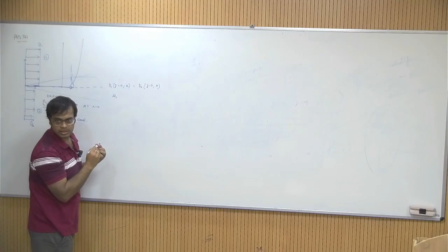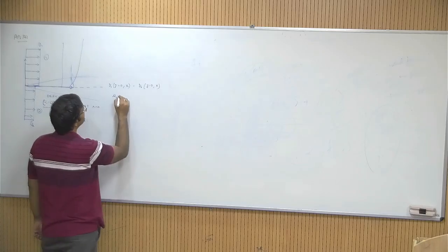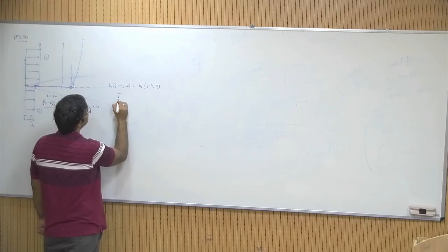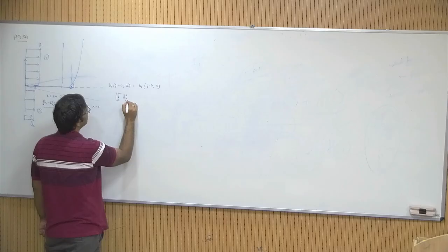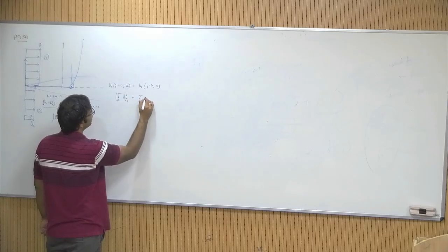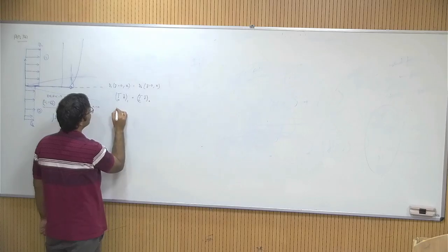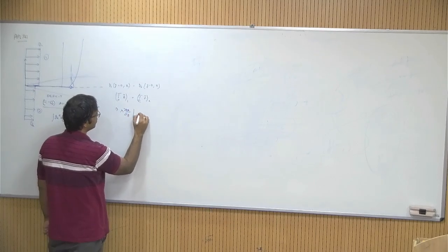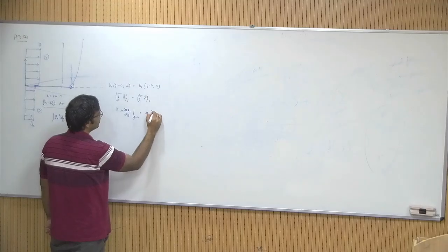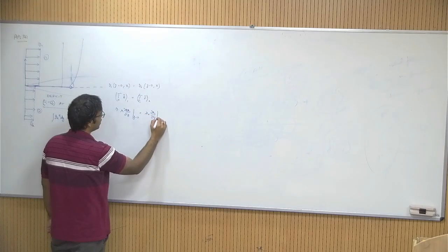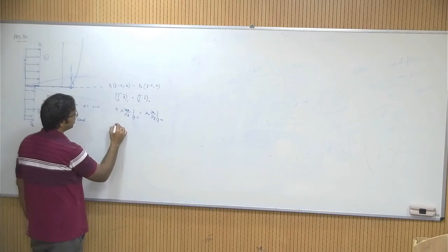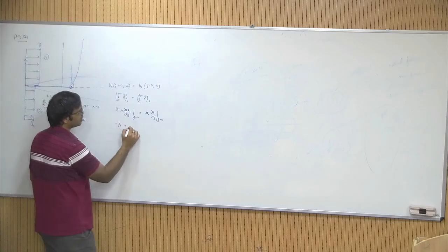and then there is another boundary condition for an interface, which is from the stress equality. So you have basically T dot n at 1 is T dot n at 2, which will give you that mu 1 del u1 by del y at y equal to 0 is equal to mu 2 del u2 by del y. There will obviously be another condition.